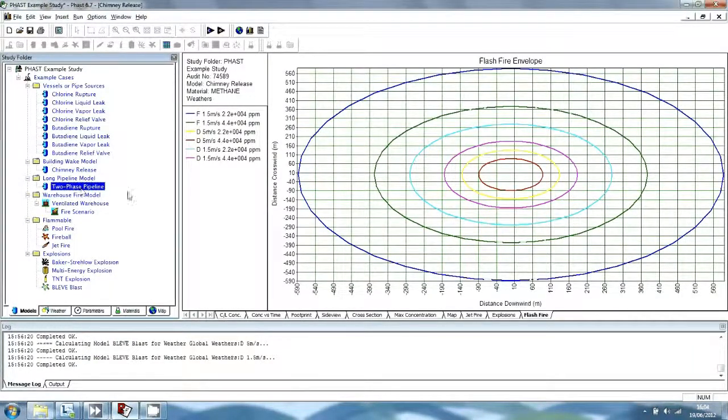The long pipeline model models the rupture of a 250 meter propane pipeline that has a pumped flow rate of 10 kilograms per second, where the rupture occurs 100 meters downstream from the pump. The program performs discharge modelling for the complex time-dependent flow regime inside the ruptured pipeline, and then performs dispersion modelling for a representative average discharge rate.